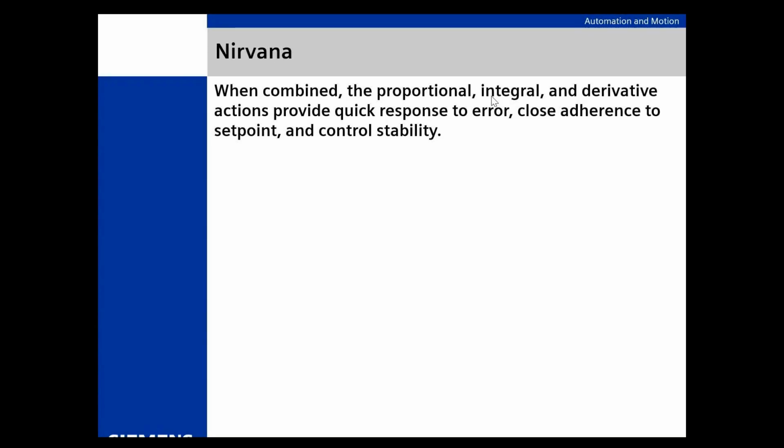Why? The chemical reaction, A, is nonlinear. B, it's not instantaneous. I'm going to overshoot every time on a pH loop unless I really get into evolved ramp soak. Add, stop, wait. Add, stop, wait. That's a ramp soak program. You ramp up, you stop, and you see what the rate of change is. You hold right there. And when it quits changing, add a little more. The steps get smaller and they get shorter. That's pretty sophisticated control. But you're right, operations.